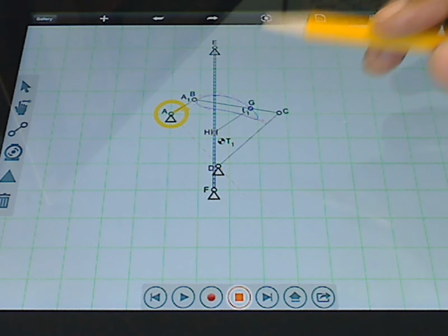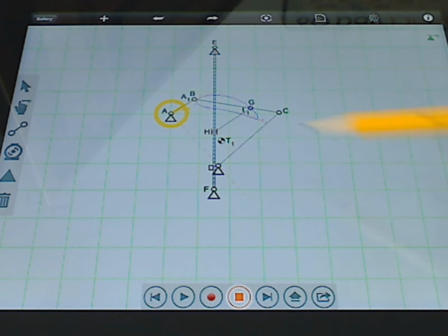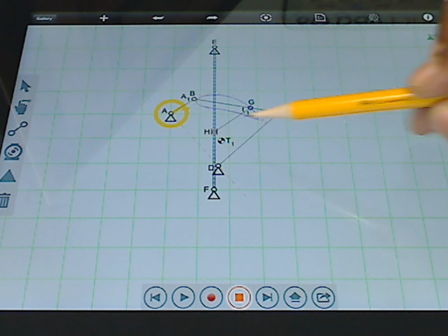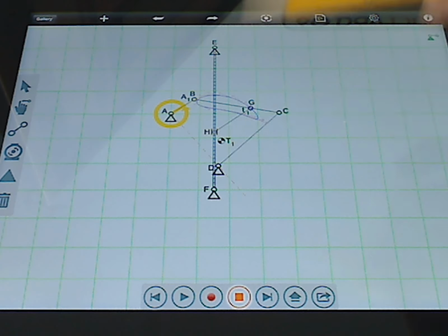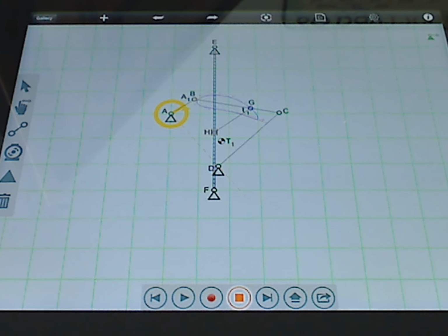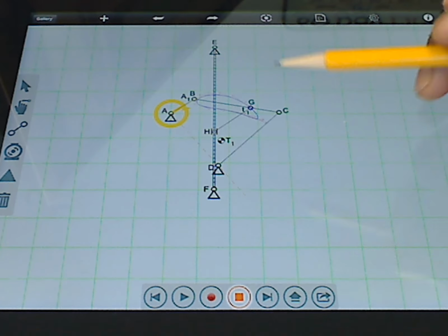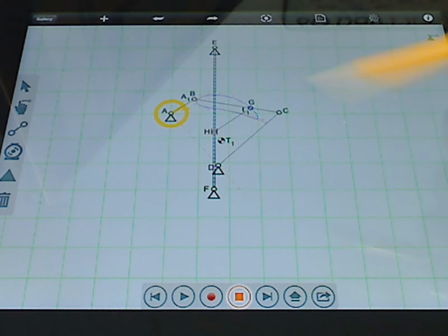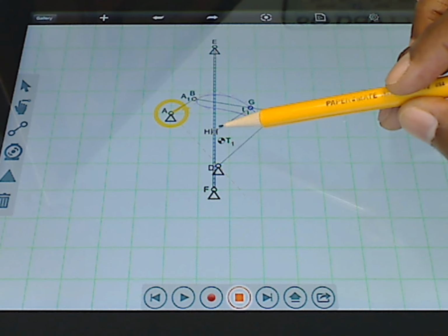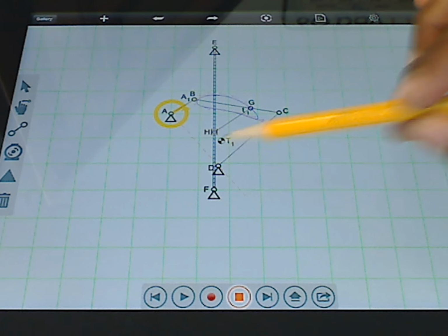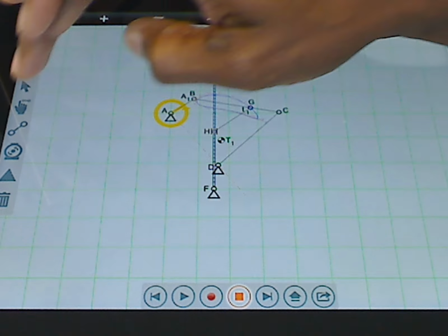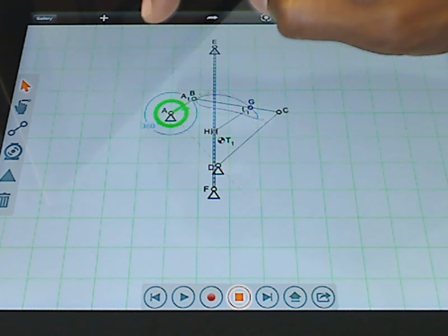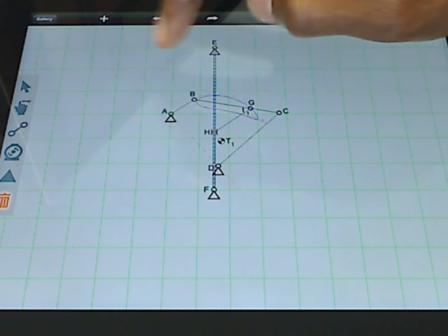Now, what we want to do next is we're going to add this bar that's in there. We already have a 6 bar now, but we're going to add an additional bar, and we're going to let that thing be our output. And what we want in this particular case is we want a 90-degree output motion while we're in dwell. So the way that's done is you need to measure the distance between the dwell position and the maximum stroke. And so if we look at this, we can kind of see, let me go ahead and take this motor out for a second.